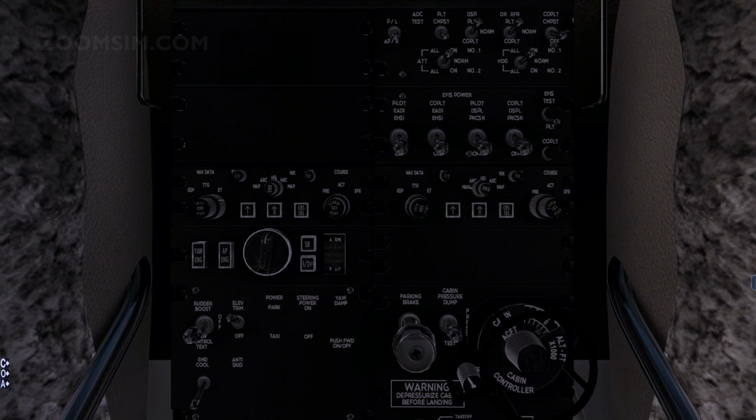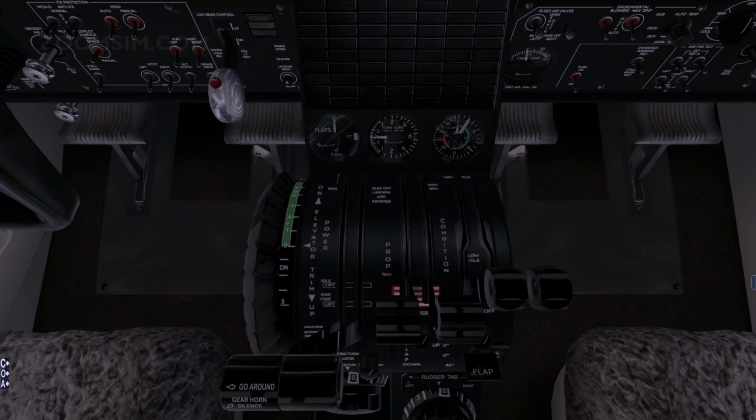The rate control selector should be adjusted as required, but the aircraft altitude should not catch up with the cabin pressure altitude until cabin pressure altitude reaches the selected value and stabilizes. As the aircraft descends below the pre-selected cabin pressure altitude, the cabin will be unpressurized and will follow the rate of descent to touchdown. Cabin pressure altitude is indicated by the cabin altimeter. The rate cabin pressure altitude is changing is indicated on the cabin vertical speed indicator.